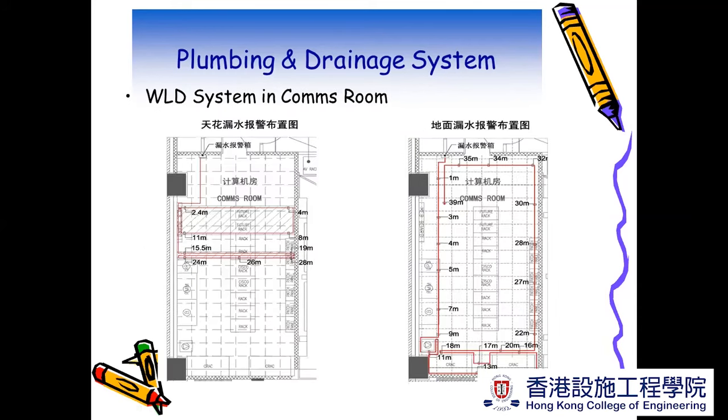In this computer room, although it's indicative that the control panel is over here, the water leak detection cable is running alongside the four walls, and maybe also below the CRAC unit, because the CRAC units always have some water tank. In case the water tank leaks over, you have some cables, but in fact it should be right along the wall.